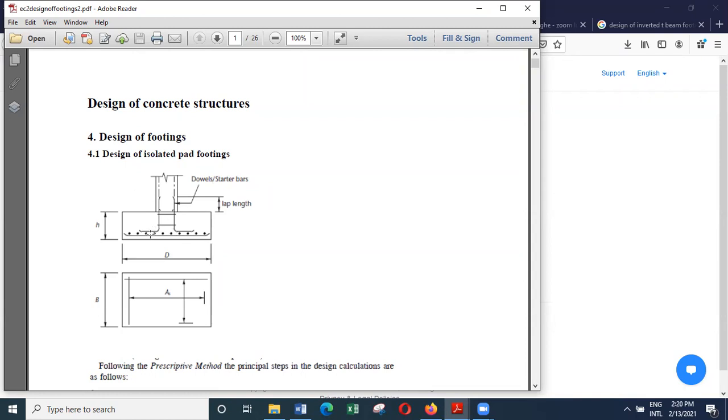And then when you are providing reinforcement, you have to provide it in such a way that the crack controlling rules are complied with. And also the minimum reinforcement that you have to provide here is the minimum specified in EC2. So you have to provide the minimum reinforcement or more. And then you also have to make sure that you comply with the crack controlling rules.